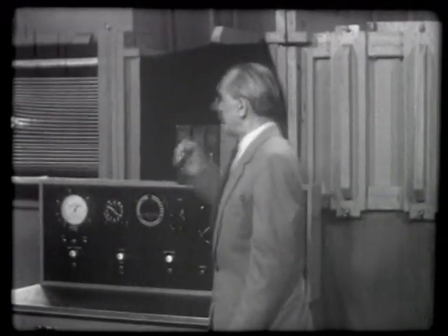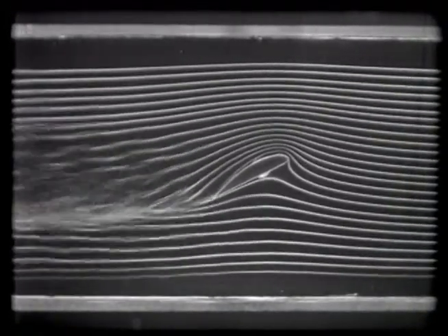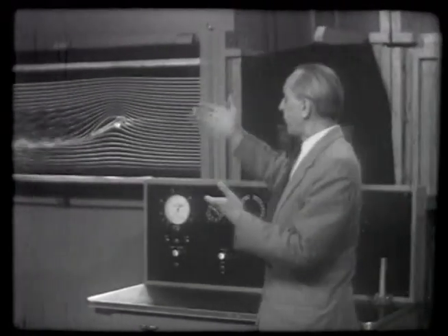Well, there is. And this is just the opposite to this boundary layer suction. It's blowing, because, see, you could also accelerate this dead air zone, this mass of air which has lost its momentum on the surface. If you would blow to it, well, then you would get almost the same effect.